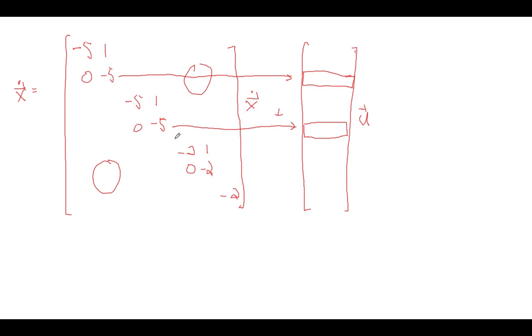But if you think about the dynamics of this, you've got two parts of your system. So this part of your system is describing state 1 and state 2, and this part of your system is describing state 3 and state 4 in this equivalently transformed state equation. But they both have identical dynamics. They both have this eigenvalue at -5, which is equivalent to a time constant of 1/5 seconds. So it's important, if I want to completely control this state to wherever I want, oh, I'm sorry that I put a little dot there, that shouldn't be there.